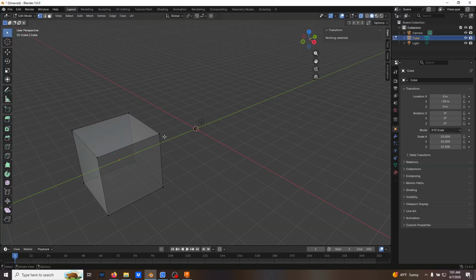Okay. Also, one more thing I want to highlight about edit mode while we're in here: when I bring up this little tab with the N button, I'll get global and local properties. So even though I scaled it up to 30 units per side, when I look at it in local coordinates, it's still 1, because I just scaled it up. The object origin gives its own coordinate system, and then I'm scaling that up to look larger in the world view here.